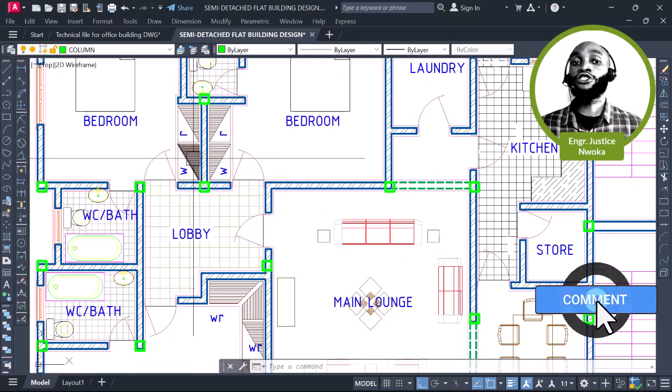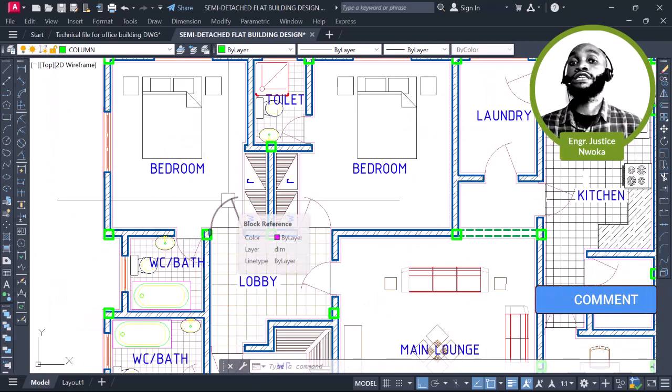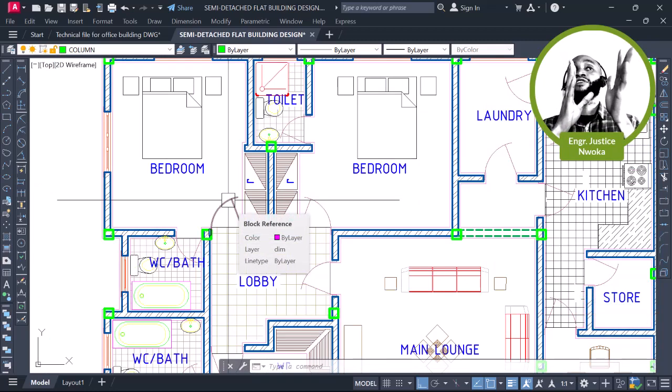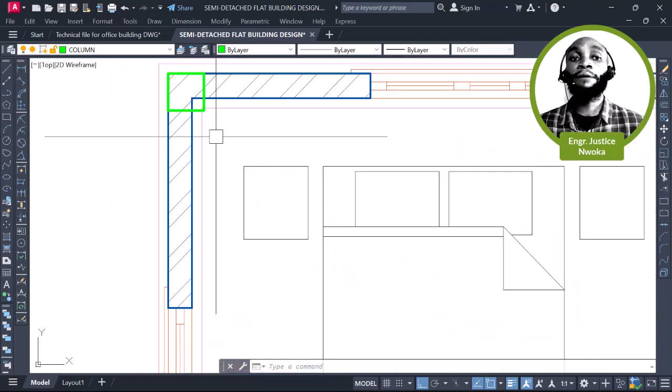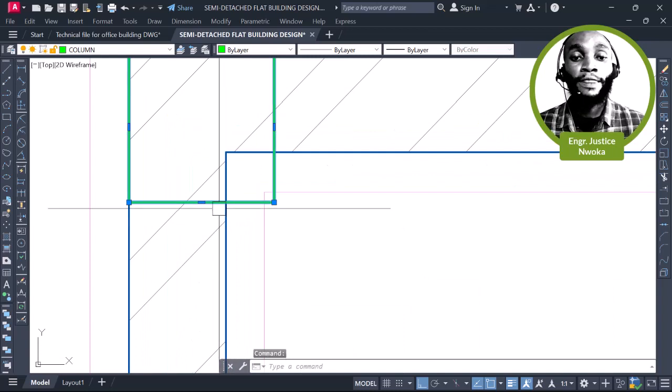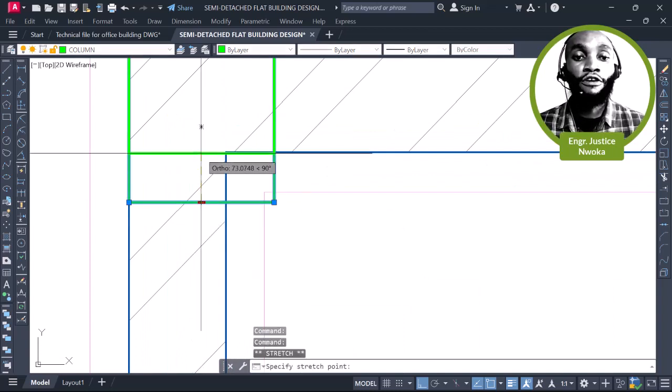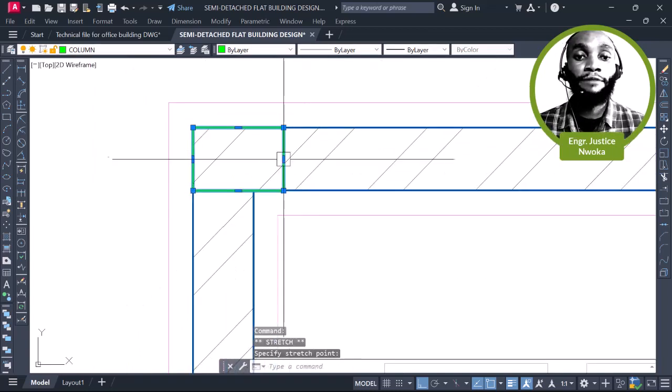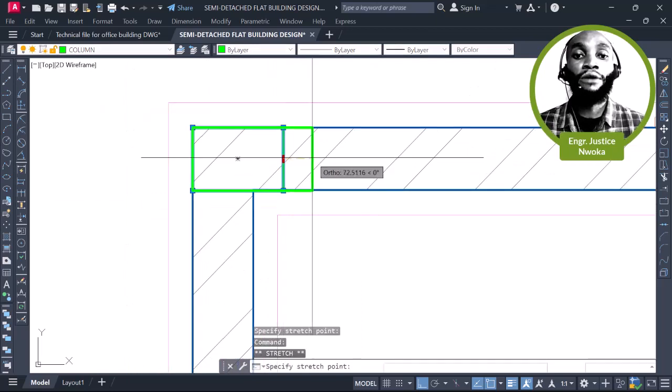But there is a way you can also follow them up on what they are doing. Since there is a 9 inches block wall, you can use a column size of 150 by 300. That is what can be best, just to meet up with the same sectional area of the column size which we took from the first time, 225 by 225. So we can still use 150 by 300. For example, we can come here, click here, keep this here and then extend here a bit by 75 additional to have 300.